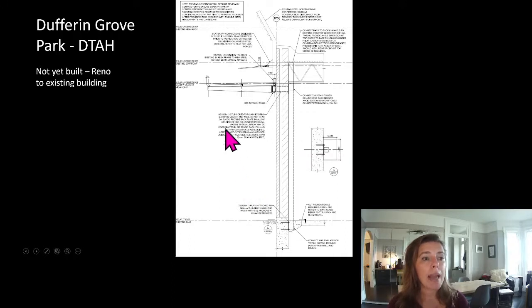So what I imagined here is that this canopy would be fabricated off-site, brought in as one, slotted into cored holes in this existing brick and block, and then connected to this steel column that would run and connect to a joist above and into the concrete wall below. So the canopy is doing this and creating our couple, similar to that Architects Alliance one that we saw at the very beginning.